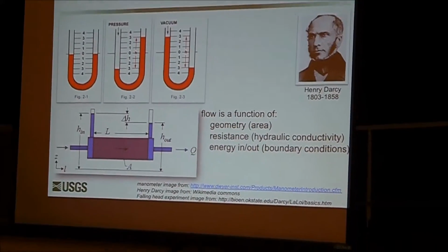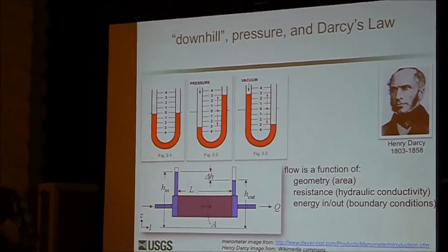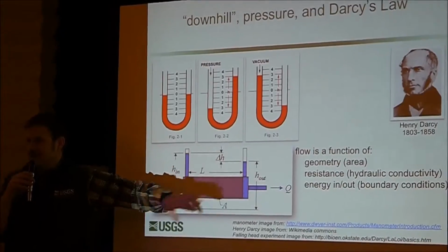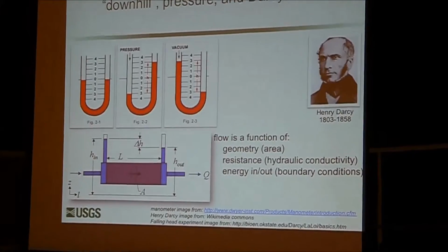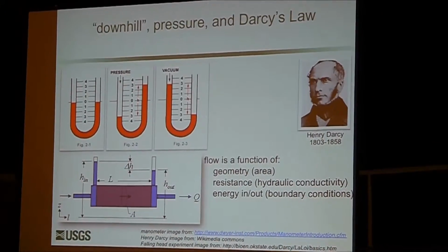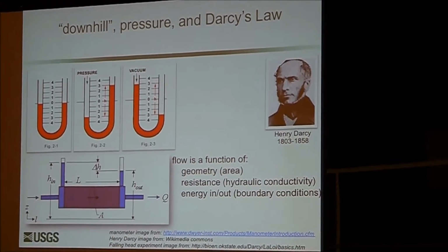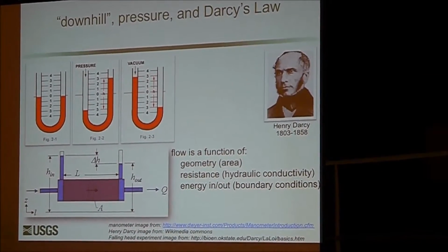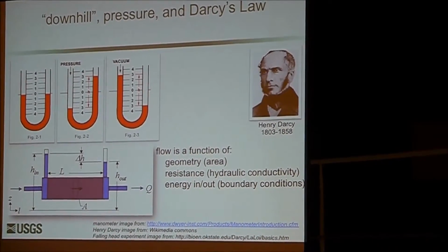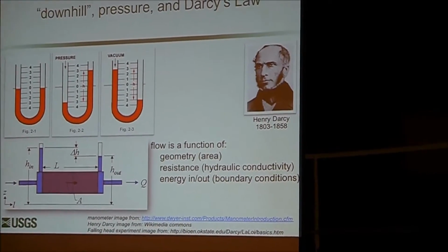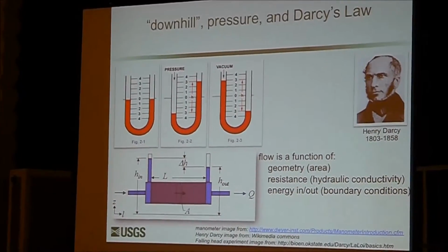That doesn't have a lot of pores, or the pores aren't very well connected, you need more pressure to move the water through. If this is like gravel or big rocks, the water will move through much easier. You need less pressure. And so there's a law called Darcy's law, which basically incorporates everything I've just said. So the mass has to be conserved, the energy has to be conserved, and there's this resistance to flow due to what the material is like. And Darcy's law basically governs everything that we do when we study groundwater.